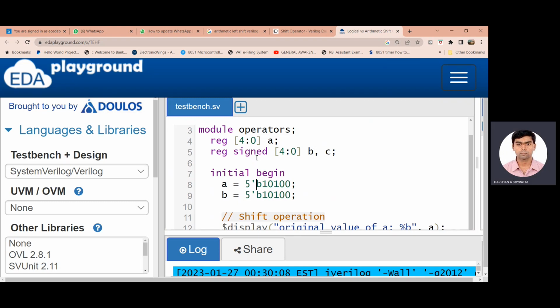Here I'm assigning some values to A and B. 5'b is a declaration in the Verilog program, because I declared A and B as 5 bits. [4:0], 4 plus 1, 0 is also considered as a 1 value in the computer. 5'b indicates a binary value, followed by some random value I'm going to declare for both A and B in order to verify the shift operator. I need to verify the logical shift operator. For that purpose, I'm going to assign some A and B values in this.